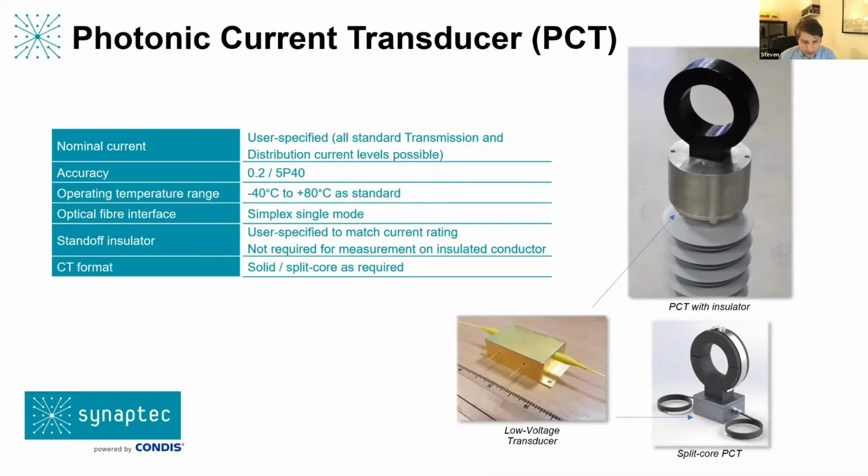It's also worth pointing out that, going beyond the substation, looking at the protection of lines, one of the common issues is how those measurements are synchronized and how they're communicated over a long distance. We provide an elegant approach to that where you don't need the conventional communications network, and you don't need to deal with the issues of migration to MPLS networks and these kinds of things, because we provide all the data back immediately where you can perform the protection function in a centralized way. So it works within the substation and at a distance as well.